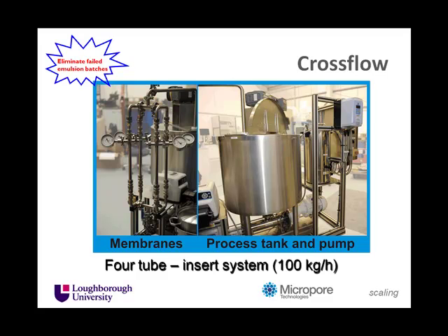Okay, so scaling it up from a laboratory system into a more commercial system, if we were looking to provide cross-flow on the membrane surface, that can give us a consistent shear, and of course the drop size is shear dependent. So here are in fact 4 tubes where we have a cross-flow consistently going, and it goes round and round from the progressing cavity pump that's down here, through the module up here, and back into the feed tank, which is just here.